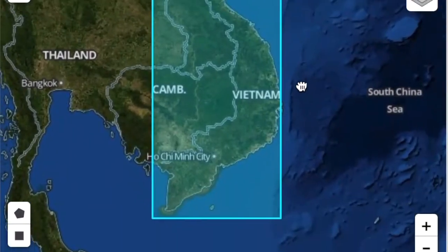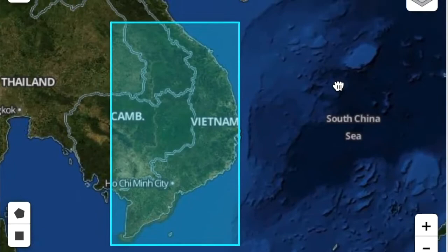I then researched which hydrological parameters are the most influential to Southeast Asian floods. I then determined the boundaries of my first study, the region of South Vietnam from 2000 to 2020. Step 1 was to batch download the necessary products from the NASA Earth Data Pool, and a program was written to streamline this process. The raw data was then pre-processed to extract the information in the desired file format, correct reference system, and filtered using quality assurance layers.